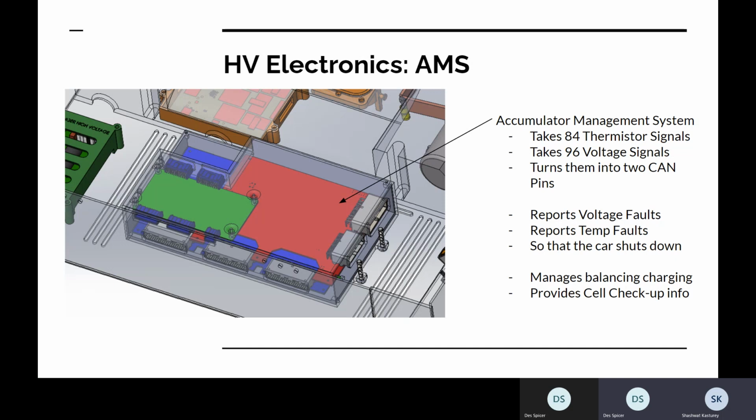Okay, that's a good catch. Since it's an electrical device that senses temperature pretty much directly, the response, as Des explained, shouldn't be that bad. For error handling of something like a fuse blowing, the reason you would want to look at voltage rather than temperature is that temperature isn't going to change all too quickly with a fuse blowing.